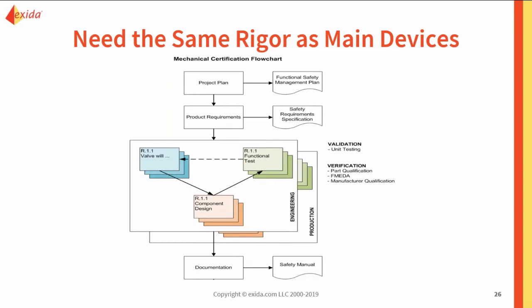Once again, it's not just good enough to take a valve, take an actuator, a solenoid, stick them together and throw them out there. Integration needs to have that same rigor, the same process, the same procedures as a device that is being thrown into this SIF. Or even if you think of it from an end user's point of view, they're doing all of these calculations to make sure that these devices will work. We want to make sure the integrated final elements for them will be reliable as well.